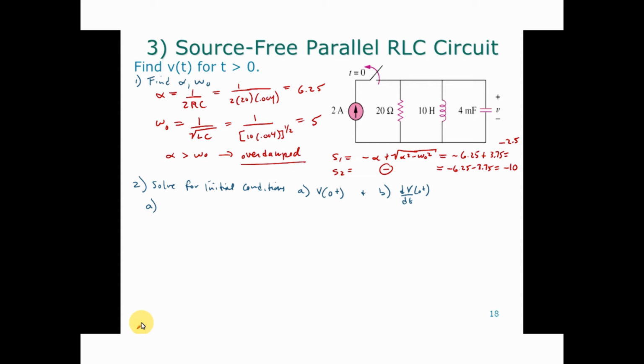So, the capacitor's an open, and the inductor's going to be a short, right? Okay. Can you now figure out what those are? So then, what's the voltage going to be across the capacitor? Okay, the inductor's a short, and the capacitor's an open. And all the current's going through what? The inductor. Because the inductor's a short. The current's going to follow the path of least resistance, right?